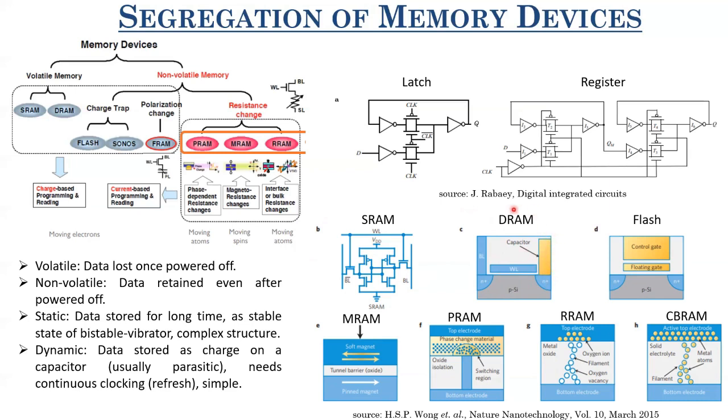Now, since this is only a 1 transistor cell, it is much smaller in area as compared to this SRAM. However, in DRAMs, it's the capacitor which is non-scalable. So in SRAMs, you scale these transistors, the size reduces. In DRAMs, transistor size may reduce significantly according to the logic node, but these capacitors are very difficult to scale. So that is one problem with DRAMs.